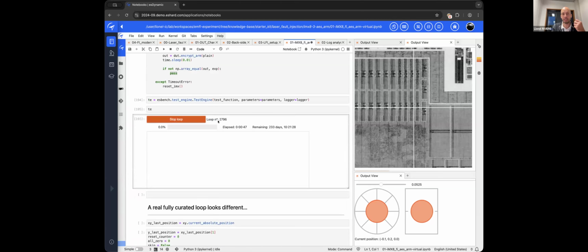So it was this test loop here. And here, for instance, after less than 1 minute, I have already injected more than 3,000 laser pulses on the chip. So it can be quite fast. If the device is fast, that's great. However, as soon as it starts to crash, everything will be slower because we will need to restart. It will need to reboot. This is why we try to minimize the area to cover, the time frame to cover, and also the failure like mute mechanisms or simply crashes.